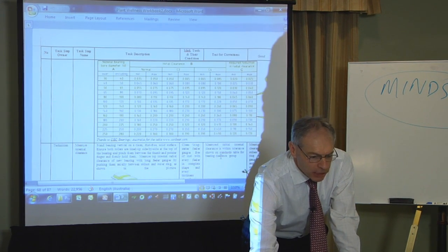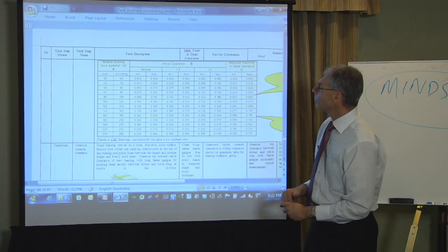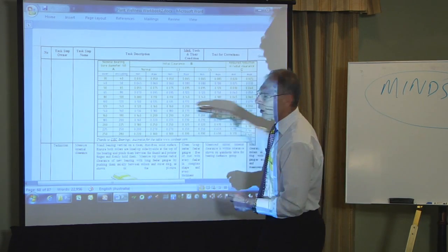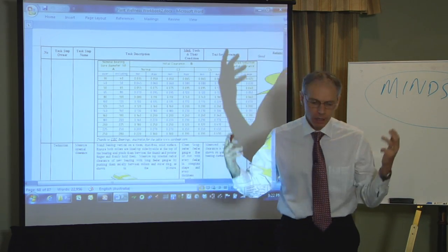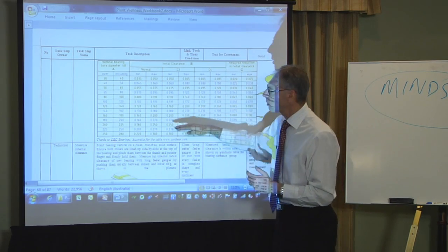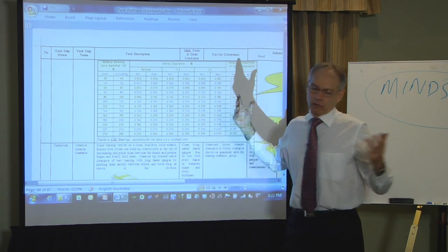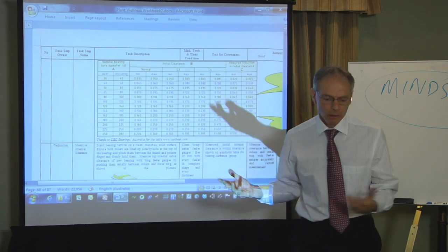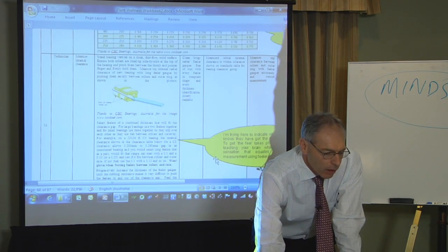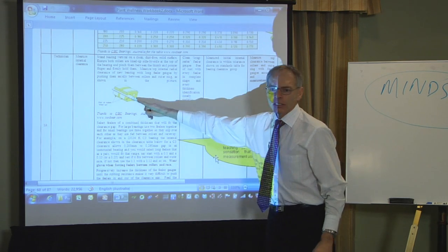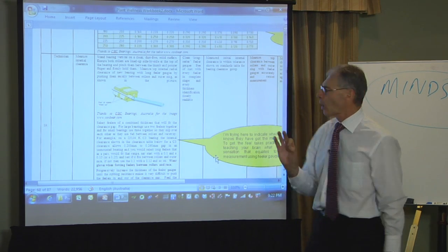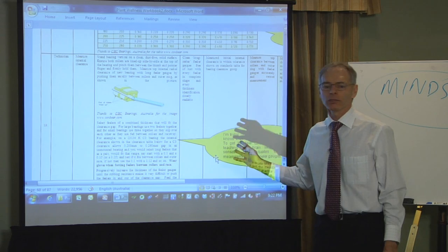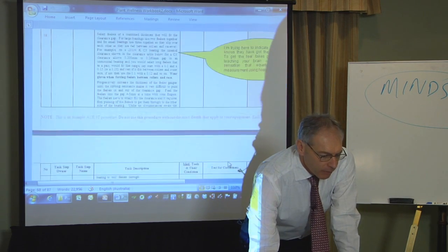There'll be tables to select clearance values from, depending upon the size of the bearing, different clearance between the internal components. Gee, I hope he gets the right line. I won't be there. Nobody else but this guy will be there. I hope he gets it right. He's going to have to check the clearance. It has to be spot on because I want to get 5 to 10 years trouble-free operation. And we go on down.